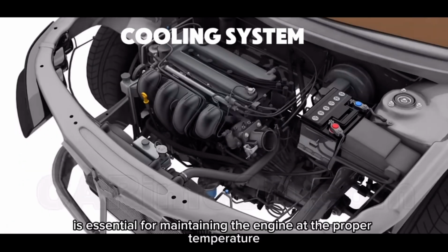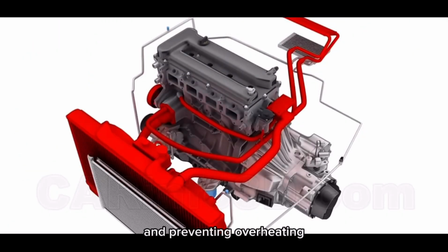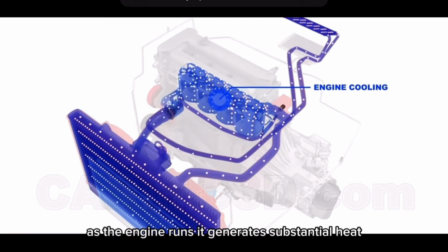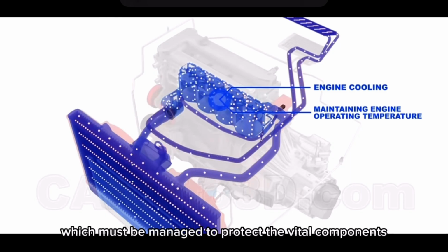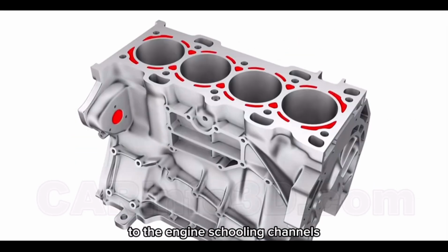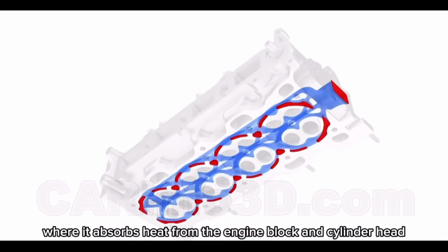The cooling system is essential for maintaining the engine at the proper temperature and preventing overheating, which could otherwise cause severe damage. As the engine runs, it generates substantial heat, which must be managed to protect the vital components. The system circulates coolant, a mixture of water and antifreeze, to the engine's cooling channels, where it absorbs heat from the engine block and cylinder head.